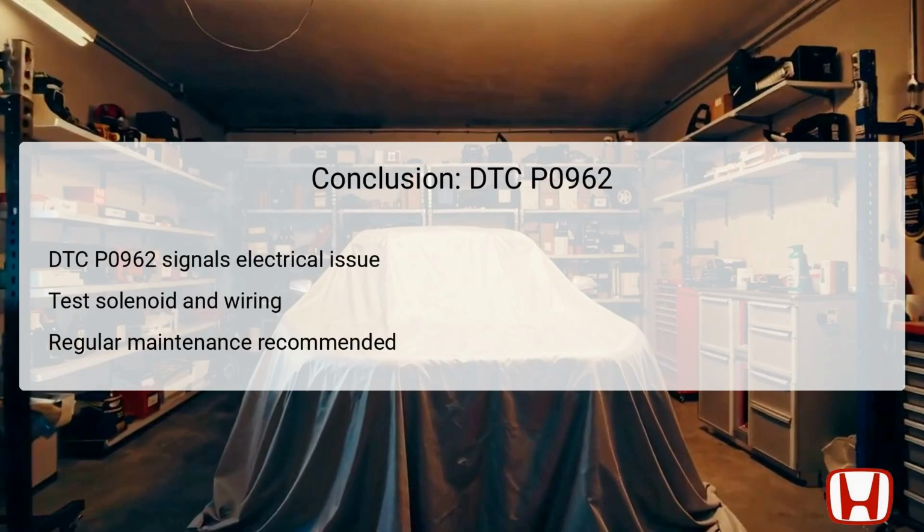In conclusion, the DTC P0962 indicates a critical electrical issue with the CVT drive pulley pressure control valve circuit. Diagnosing and rectifying this problem involves systematic testing of the solenoid valve and wiring, ensuring all components function as required. Additionally, preventive maintenance measures, such as regular inspections and updates, can significantly reduce the risk of encountering this code again.